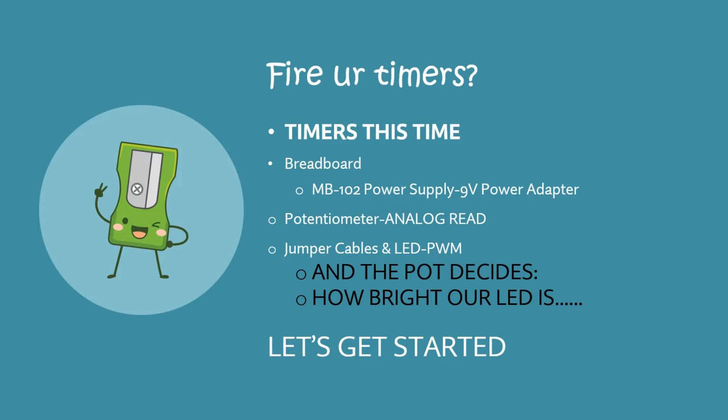The setup remains the same: an MB102 power supply adapter with a 9-volt power supply that's used to power a potentiometer. The potentiometer gives an input to the Arduino Uno's analog pins, and this analog read value decides how bright an LED is going to shine, and the brightness of the LED is decided by the PWM input to it.